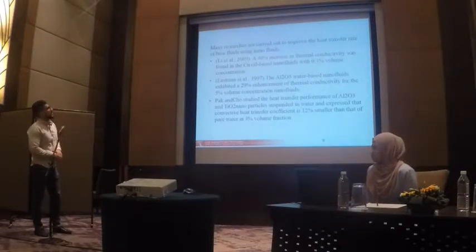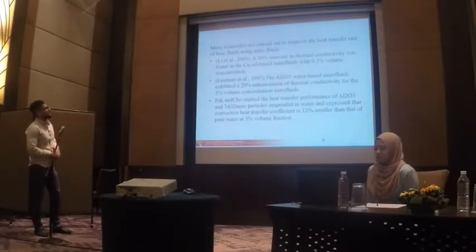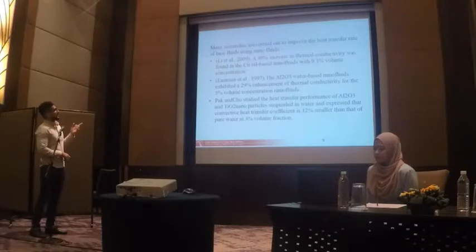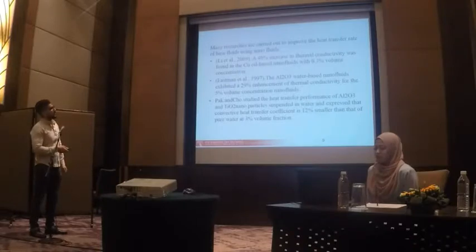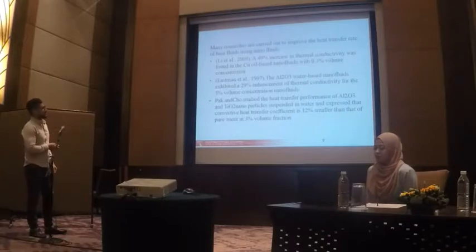Many researches are carried out to improve the heat transfer rate of base fluid using nanofluid. So Mr. Lee, from his results, found a 40% increase in thermal conductivity in CuO oil-based nanofluid with 0.3 volume concentration.